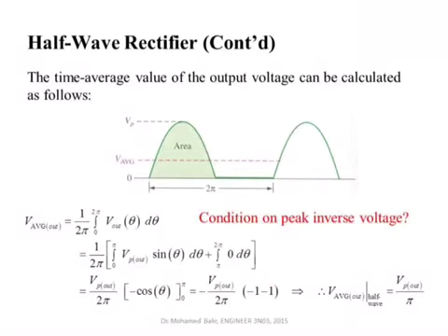Okay, and of course, you will still have this negative sign here. So this will give you 2, which will cancel out with this 2. So you end up with your average being simply equal to the peak value divided by pi. So for a half-wave rectifier, the equivalent DC that you will get is simply equal to the peak value of the sinusoidal signal divided by pi.